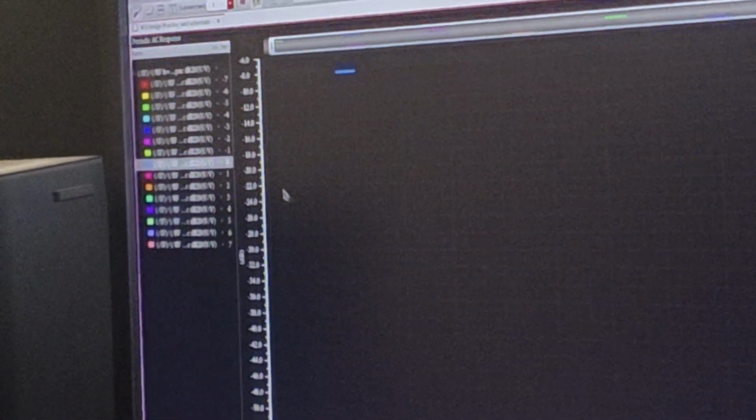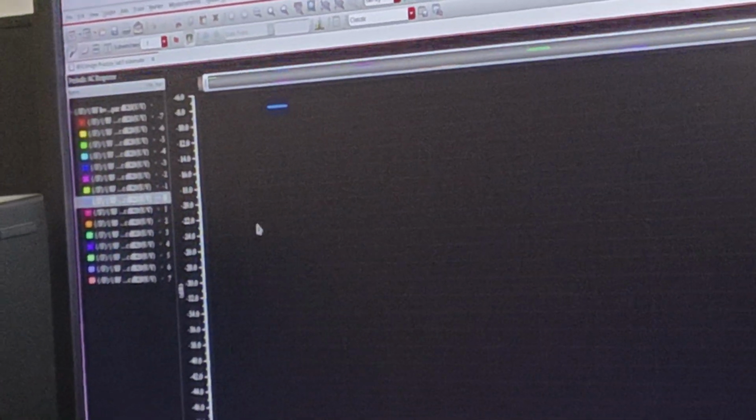Okay. So this is not only for this harmonic it will work, because our LO is having all the harmonics. FLO is there, 3FLO, 5FLO, all these harmonics are there. So if you see the next one, minus 1, with respect to minus 1 or plus 1, where it is, they are down converting. With respect to the fundamental, this came to 0. This is from the second harmonic, means 2FLO if it down converts it comes here. 3FLO if it down converts it will come to the second one, like that. Second, third, these all different harmonics exist. These are all different harmonics where they are present.